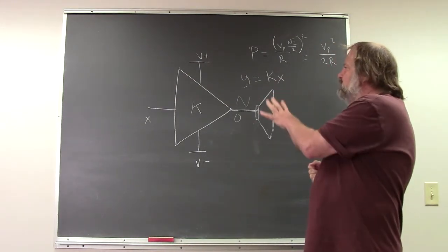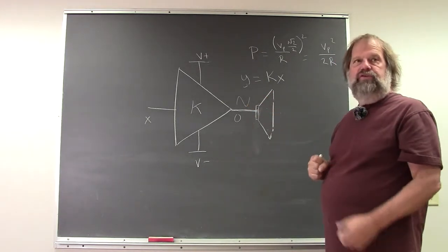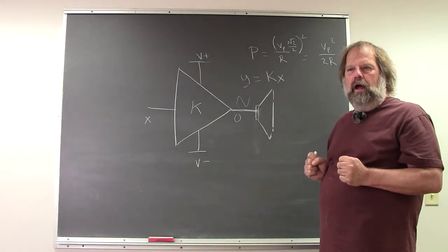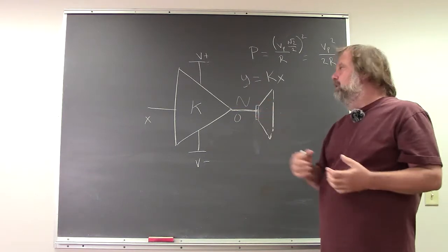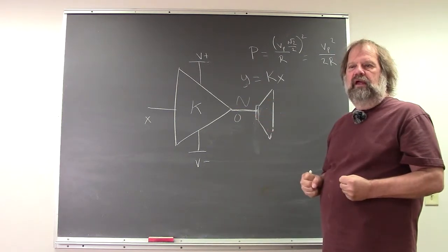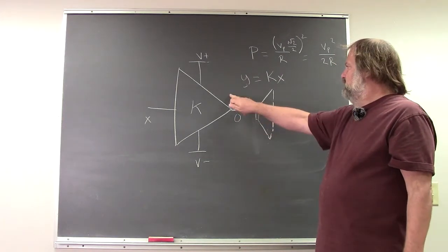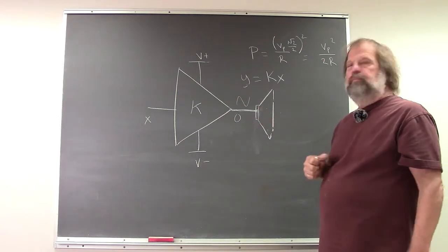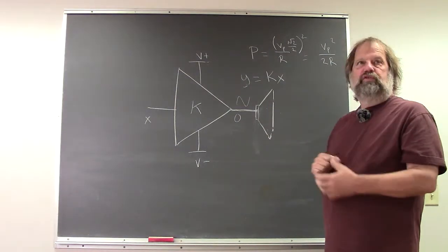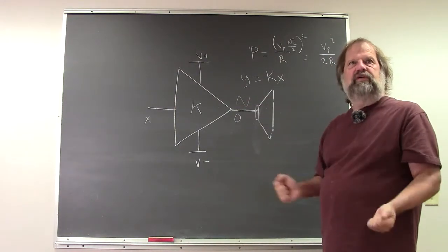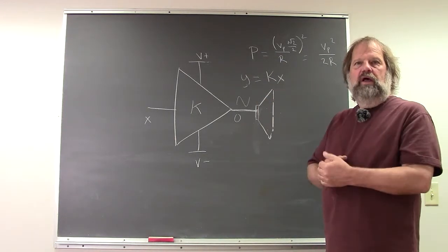So if we're doing linear systems, then the amplifier needs to be big enough to supply enough voltage for that transducer to be as loud as we possibly want it, and after that it doesn't matter. So if we've decided this driver has to be 120 dB in loudness, and it takes some voltage to do that, more than that doesn't help us anymore, because we've hit our limits. At some point, the loudspeaker is also not linear because it hits excursion limits, other kinds of things. So we make some determination of how big the amplifier should be based on the sensitivity of our